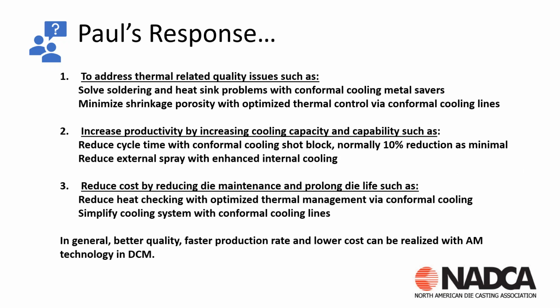So when we're looking at additive manufacturing, we're basically doing this for a few reasons. We want to address the thermal problems in our die cast tooling that are related to quality issues. So if we're seeing shrink porosity, we're seeing leakers, those kind of events, those are things that conformal cooling can assist, because we can then move the cooling right down to the shrink areas where shrink is forming. We can change the solidification in those areas.